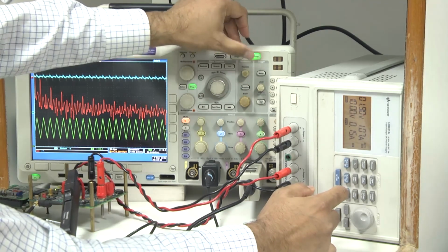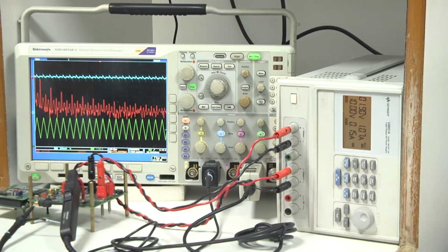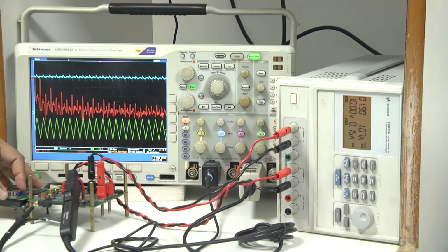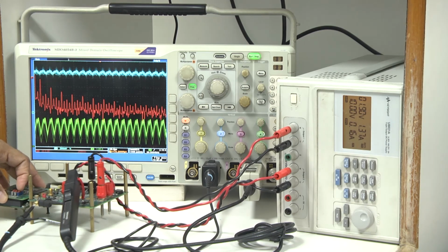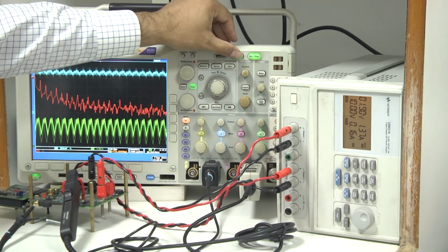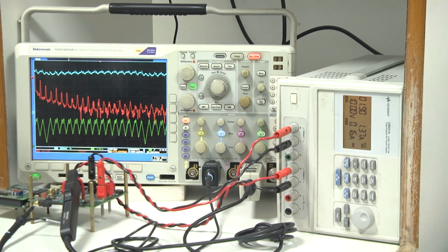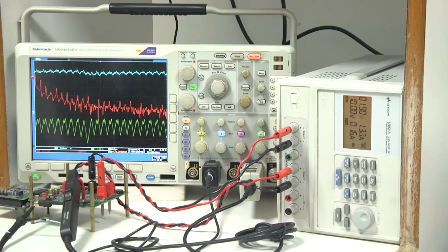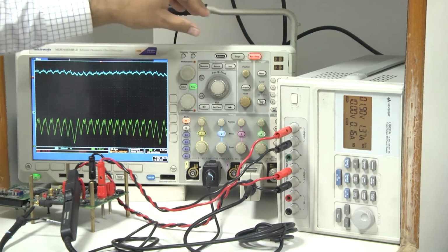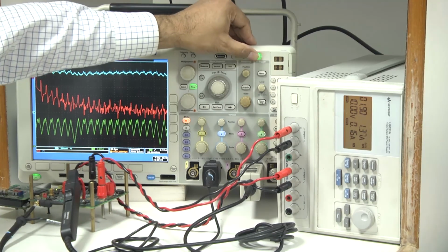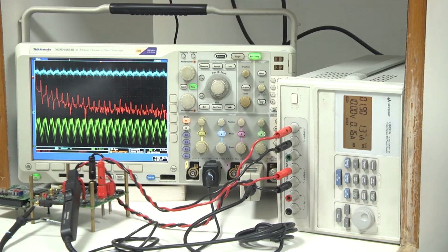Now we are going to start the ramp compensation. At this 1.9 volt there is a provision of a switch, and this switch we are giving externally. If we consider this switch, now we have added a ramp, but it is a very slow ramp. If we add this ramp, you see the nature of instability changed. That means something is happening; it is not actually stable, but there is some improvement in stability compared to the earlier case when it was totally looking like 100 kilohertz.